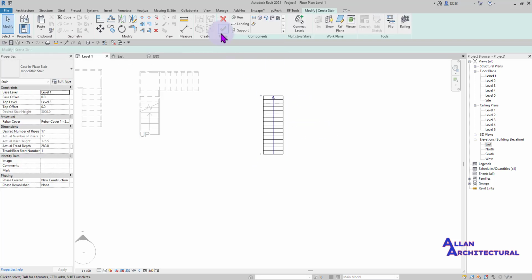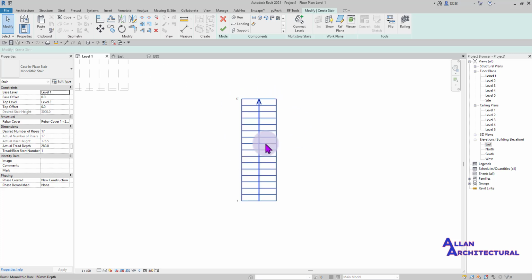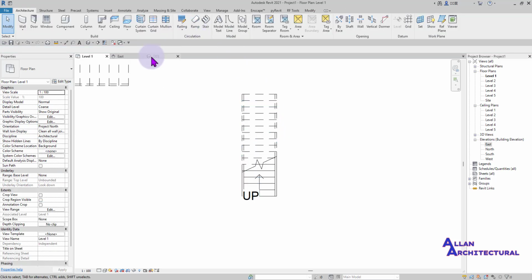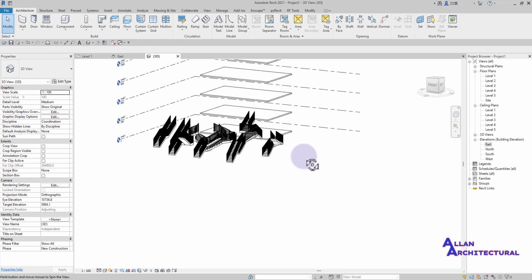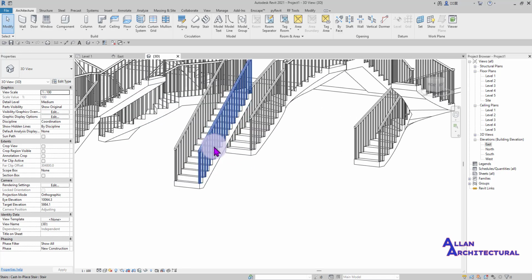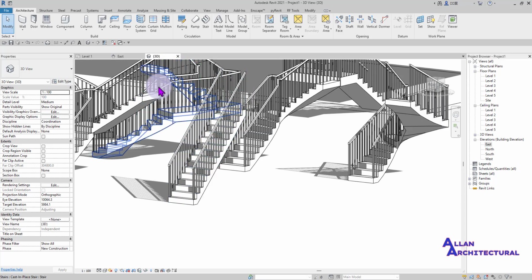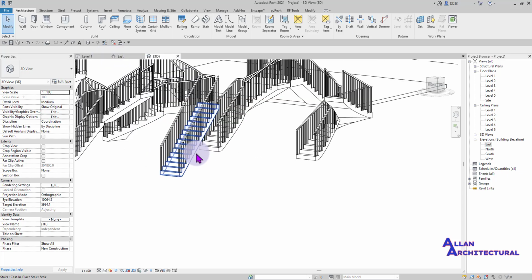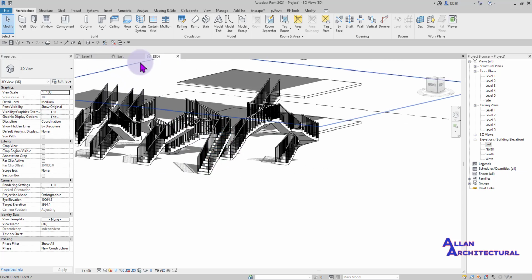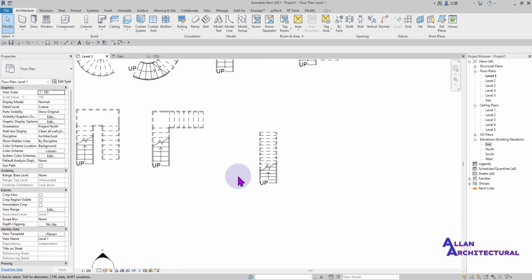And then you notice we have that staircase created, which is 1 to 17 risers. So you can finish that, and Revit is also going to automatically add railings. So this is our staircase we created by using the sketch tool. All right, so this is perfect. You can actually get every kind of staircase to a sketch mode.